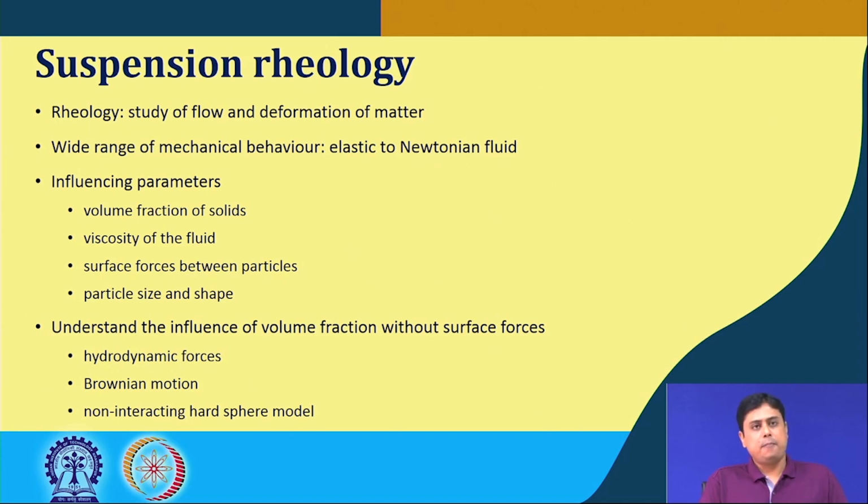In these cases, the influencing parameters of this rheology are the volume fraction of the solids in the suspension, the viscosity of the fluid, the surface forces between the particles, and the particle size and shape. All these parameters influence this suspension rheology.